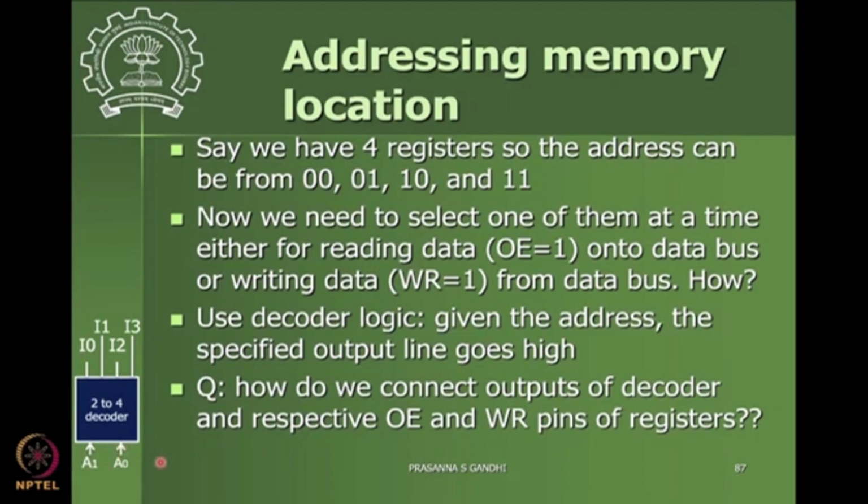The address bits and the data bits are independent of each other. I can have 3-bit data or 8-bit data, but the number of registers is what matters for the address. If I have 10 registers, that determines the address.